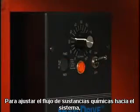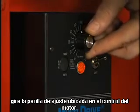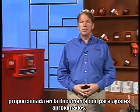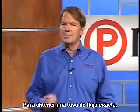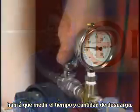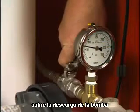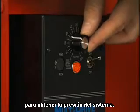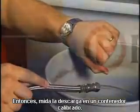To adjust the flow of chemicals into the system, turn the adjustment knob on the motor control. Use the flow rate chart provided in the product documentation for the approximate setting. For an exact flow rate, you will need to measure and time the discharge by simultaneously throttling the ball valve on the discharge side of the pump and adjusting the motor speed control to obtain the system pressure. Then measure the discharge in a calibrated container.